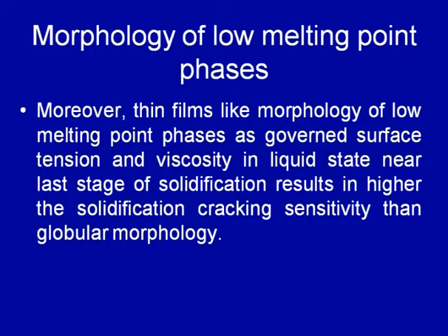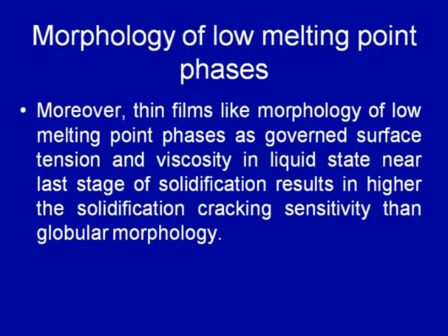Then the morphology of the low melting point phases. Many low melting point phases are formed during the welding of aluminum alloys and steels also. So, in case when the low melting point phases are present in the form of thin films, this kind of morphology is more sensitive towards solidification cracking as compared to the case when the low melting point phases are present in the form of globules.